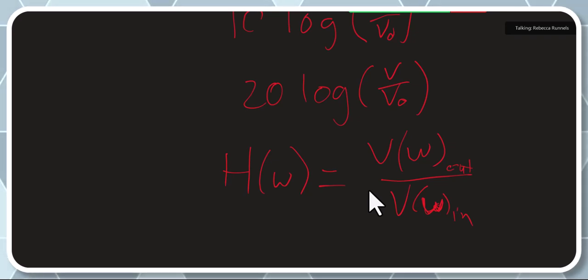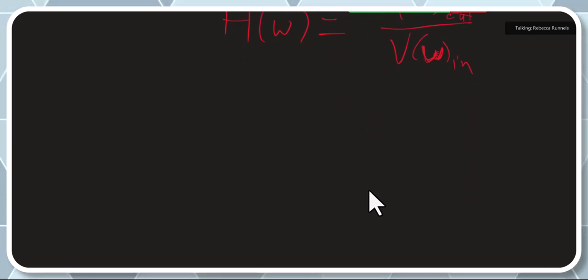The phasor angle, what about for the one in resonance, would it be the impedance angle also? Yes, it is. And that is actually a good point, because let's say I'm working this power problem and I just don't feel like I have enough information. He didn't give me the power factor. How am I supposed to do this without the power factor? But you know what the impedance is? If your impedance is 5 minus j10, then you have your power factor.